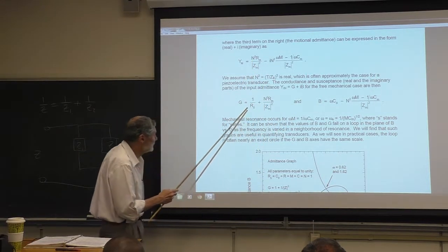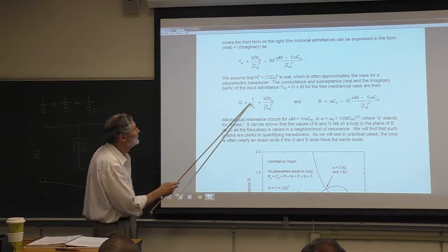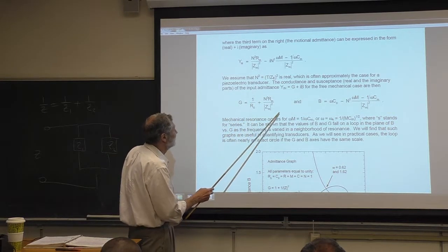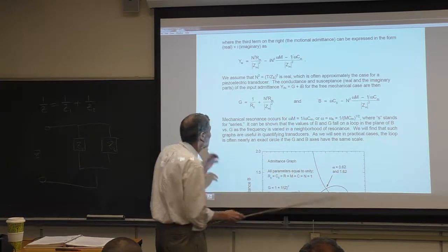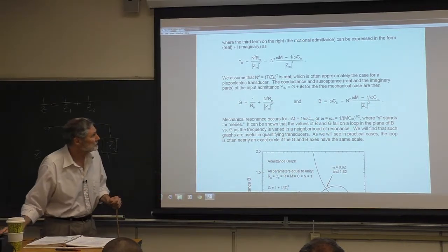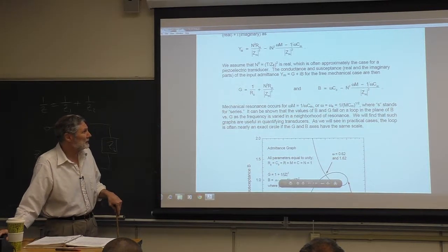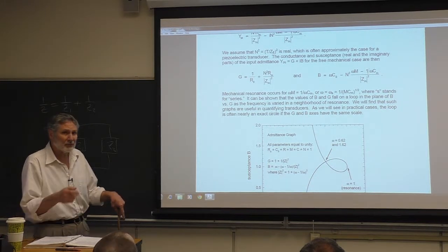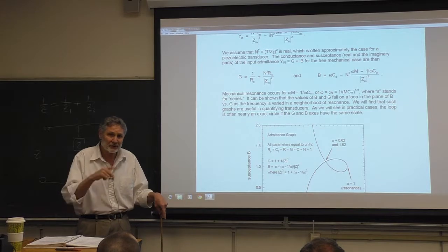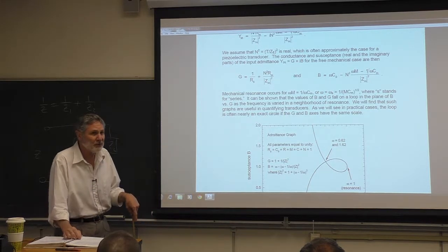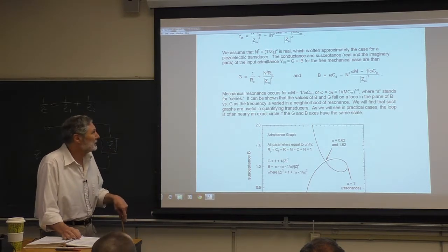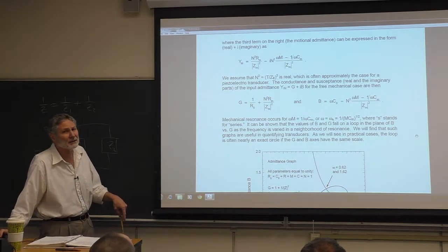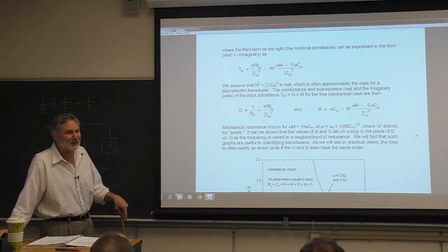And now we identify the real part, the conductance, and the imaginary part, the susceptance, here. Now, Brian keeps referring to admittance circles. A resonance has the signature of a circle, and transducer people use this word circle. And it really annoyed me because I couldn't prove that it was a circle in general. I tried. It gets pretty complicated, okay?